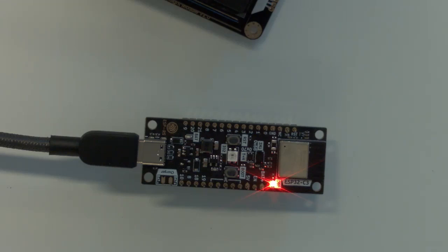Okay. Well then how come changing the duty percent can make it dimmer? Well, it's just on for less of the time. So to our eyes, it looks like it is dimmer, but it's actually just on for less of the time. To us humans who have flawed eyeballs, it looks dimmer, but it's actually not dimmer. It's actually flashing. If you had a slow-mo camera, you would actually see it turning on at full brightness and off.